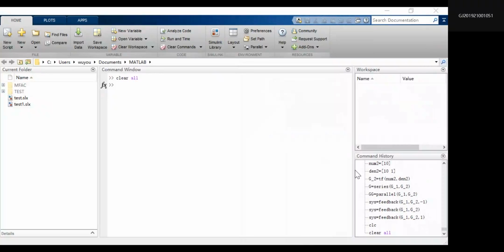It's 10 seconds. But we set the step to happen at 20 seconds. So what you're seeing here is just the 10-second curve. The time is not enough. So you should enlarge the simulation time here to make the scope show the whole curve. I think it should be bigger than 20. So maybe 50, and then you can save it first. Maybe just TT. Okay.